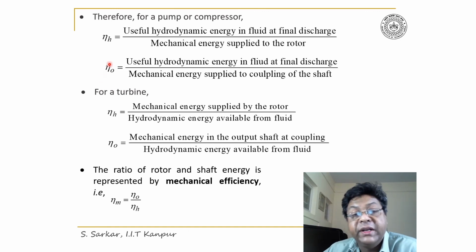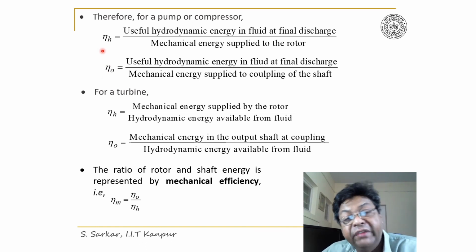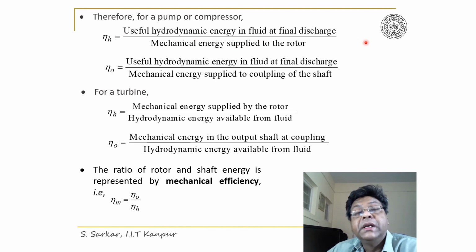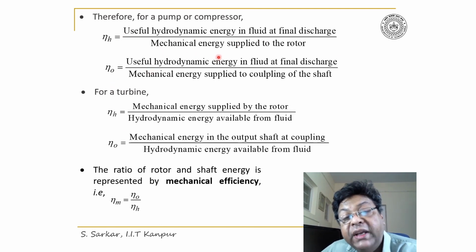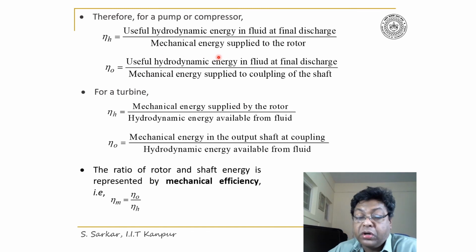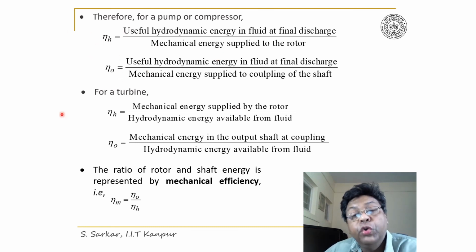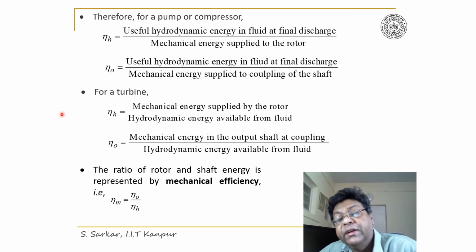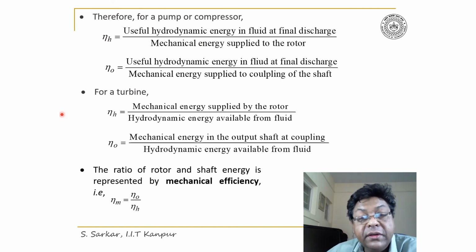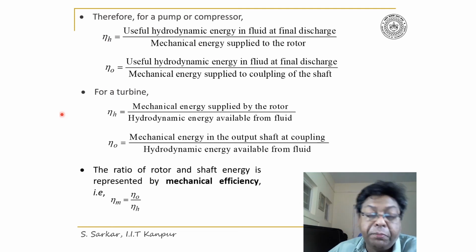Thus, I have defined hydrodynamic efficiency eta H as the ratio of useful hydrodynamic energy in the fluid at the final discharge divided by the mechanical energy supplied to the rotor, and overall efficiency as the useful hydrodynamic energy in the fluid at the final discharge divided by the mechanical energy supplied to the coupling.